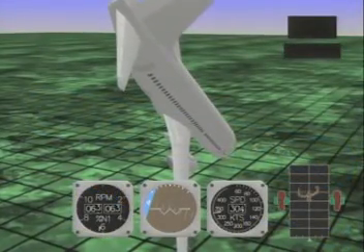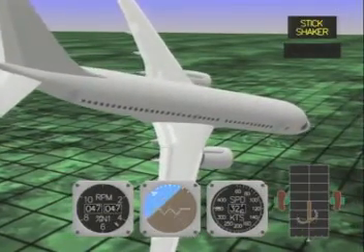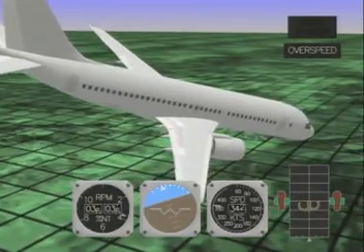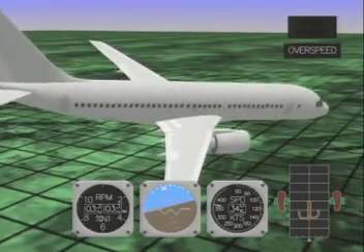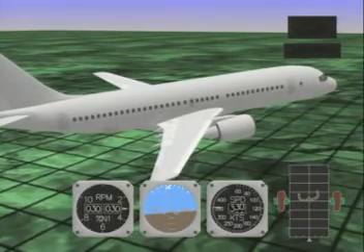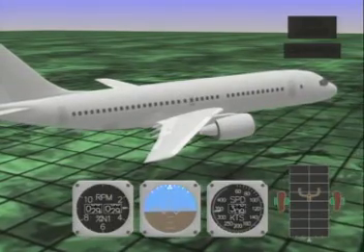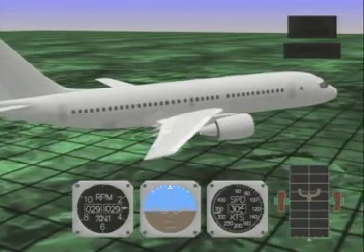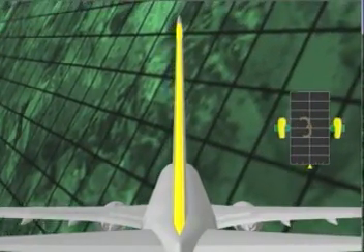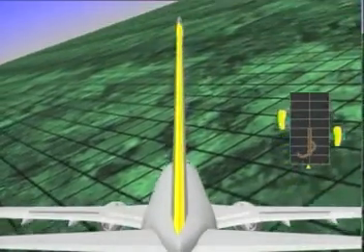In this situation, it may be necessary to unload the airplane by decreasing back pressure or even pushing to obtain forward elevator pressure. Use full aileron and spoiler input if necessary to smoothly establish a recovery roll rate toward the nearest horizon. It is important to not increase G-force or use nose-up elevator or stabilizer until approaching wings level. If full lateral control application is not satisfactory, you may need to apply rudder in the direction of the desired roll.